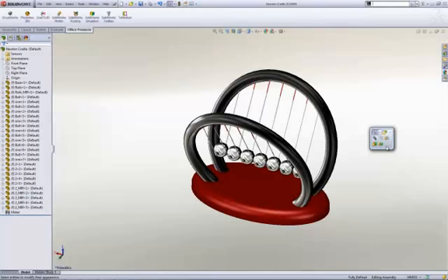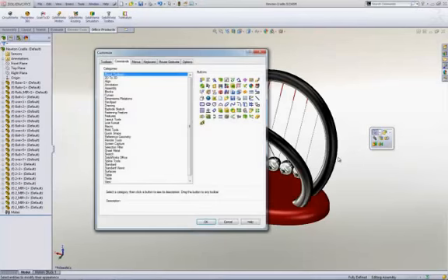And once you've launched this toolbar, if you right-click on it, here's the option that you have to customize this. So you can drag and drop commands onto this toolbar, and it's going to be different whether you're working in an assembly, a part, a drawing, or a sketch. So it's just another way that you can access commands right next to your pointer.